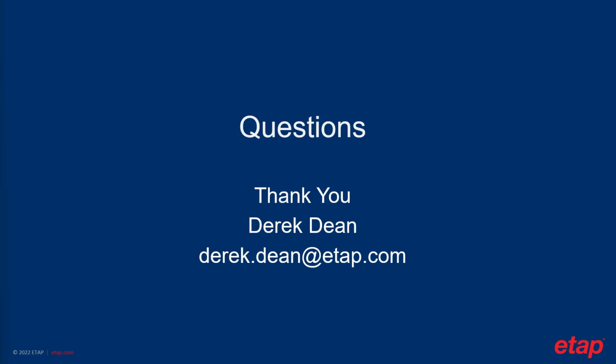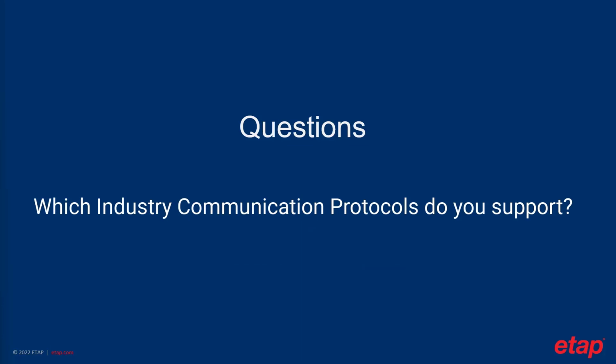questions. One question I have here is, what industrial communications protocols do you support? So natively we support Modbus, DNP, IEC 61850, IEC 104, ICCP, OPC-DA, OPC-UA. Now, there's many different converters from OPC-UA or OPC-DA to other protocols. So the long story short is I haven't found a project where we haven't been able to get